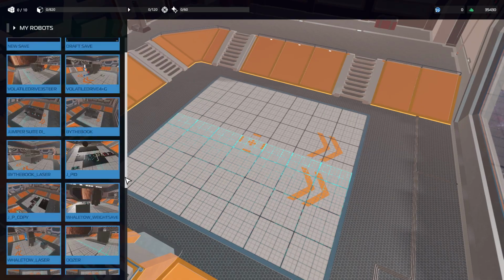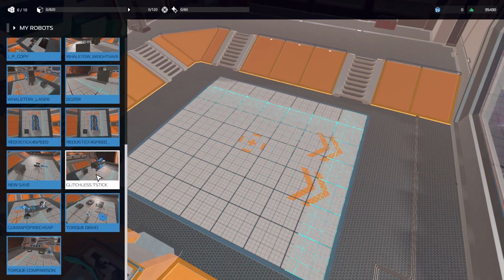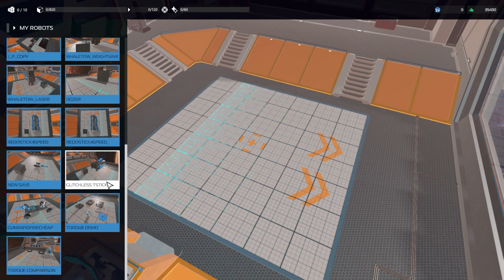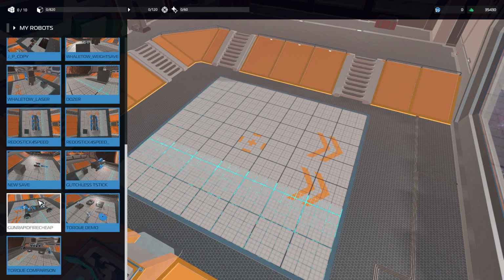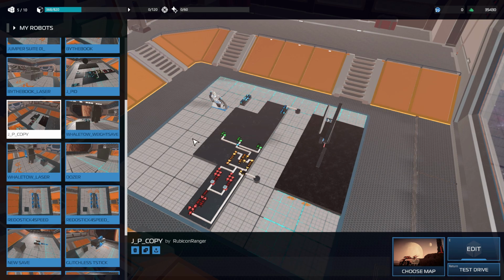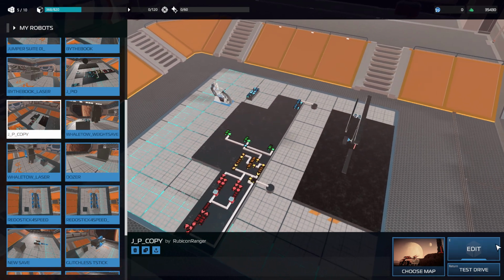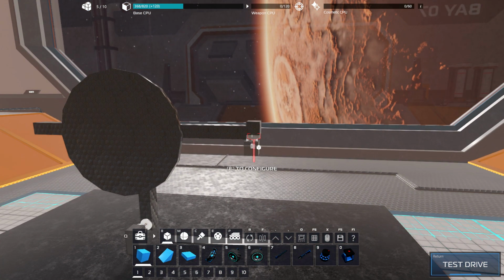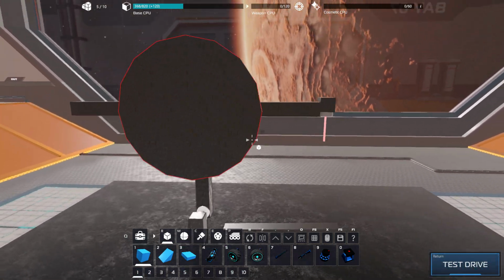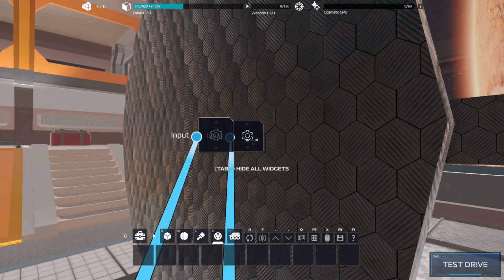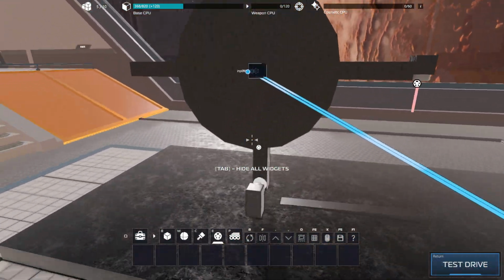And of course you can increase the mass on gyros to give them more of a range of wind-up, so a little smoother control. And then one more thing I wanted to cover. So here's just a normal, I'm making a PID controller, but let's ignore that. This is just the proportional hooked up, which basically means it takes the error from a sensor, and if it's positive, your plant model, in this case our motors here, get spun one way, and if it's negative, they get spun the other way.